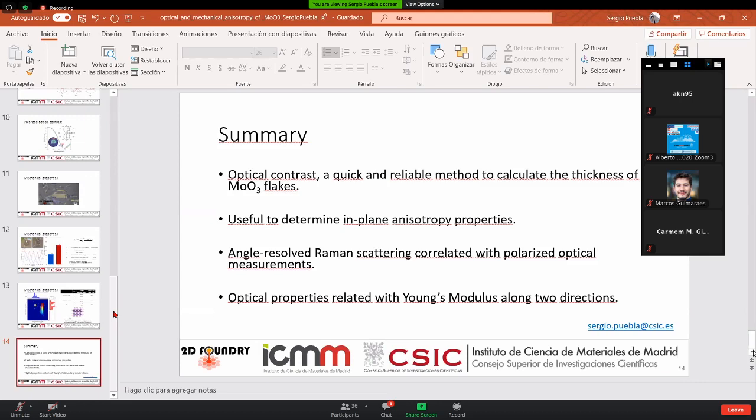So the molybdenum trioxide flakes started to grow onto a silicon wafer that we have placed onto the molybdenum foil, and these flakes, then we transfer them with PDMS with a deterministic transfer setup onto the silicon dioxide substrate that we have already shown.